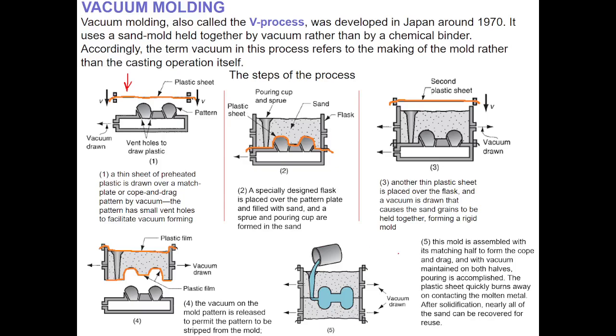Okay, that is the technology. Since we have no binding material, the sand particles are not bound to each other. After the solidification stage, we can reuse the sand particles for the next molding stage. So we can recover the sand and reuse it.